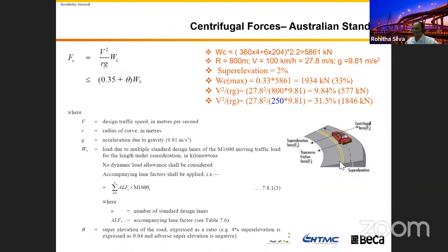When the car is moving around a curve, there is a centrifugal force pushing it away, and the counterweight of the car pulling towards the center of the circle is the advantage. If the curve is tighter, the road designer will come up with a higher super elevation. You can see this theta is negative, then this maximum value gets less when you increase the radius.